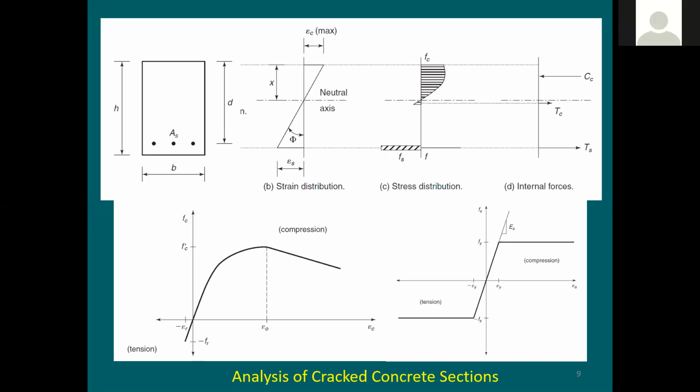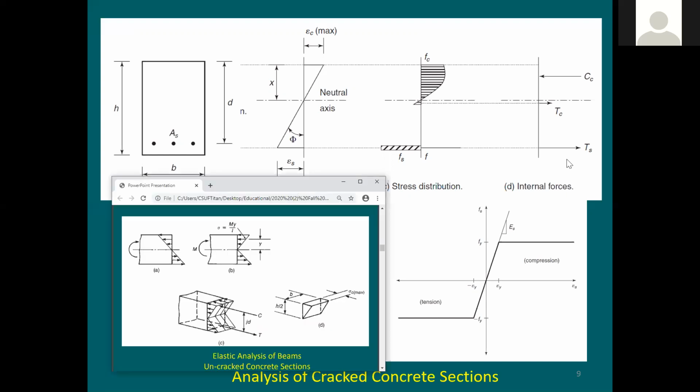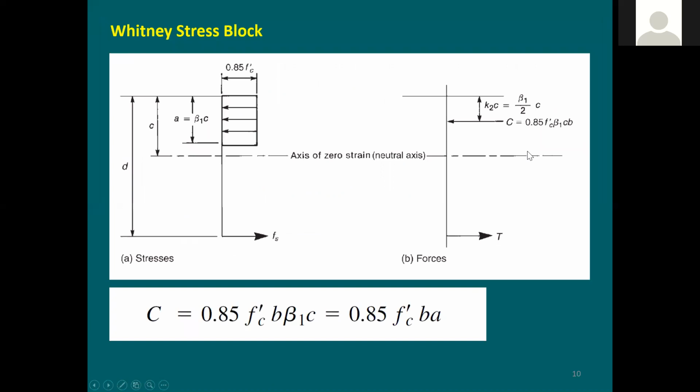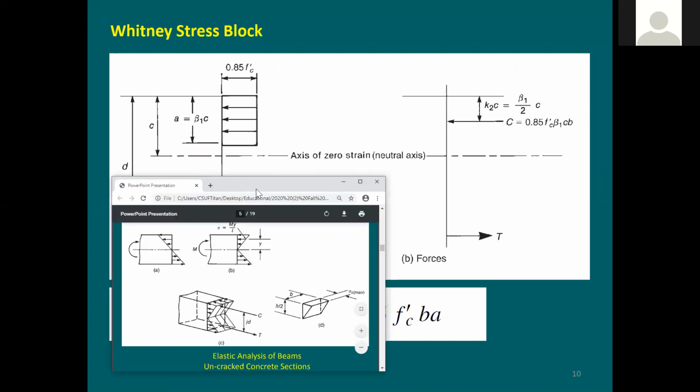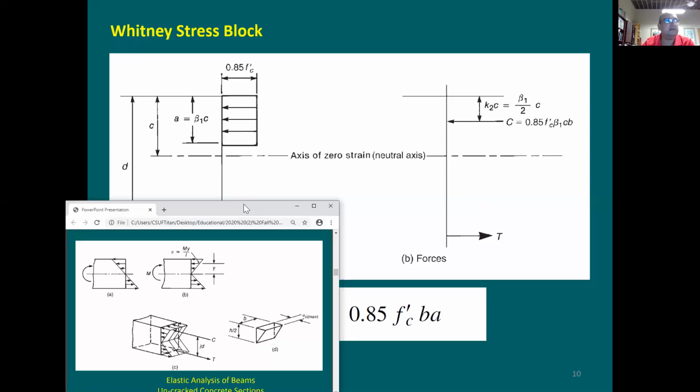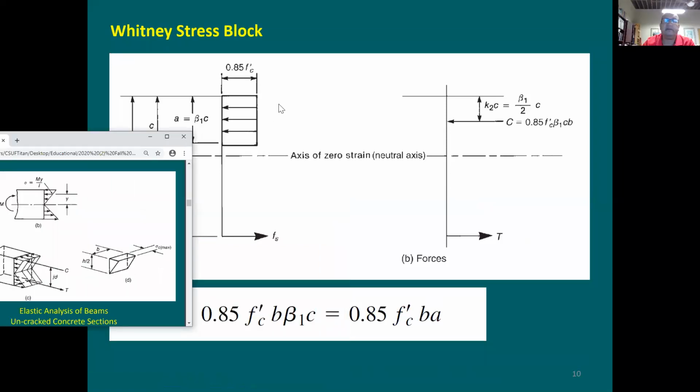Yes, so the simplification part is only for the compression, only for the top part, right? Doesn't include the small tension section. The small tension in the concrete is gone. Okay. This tension in the concrete, this little piece, we don't have it anymore. Look at this. This is now going to be the analysis, right? You just ignore it, or? It is included in here.